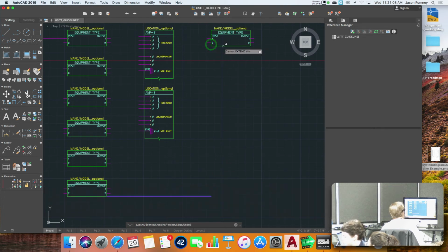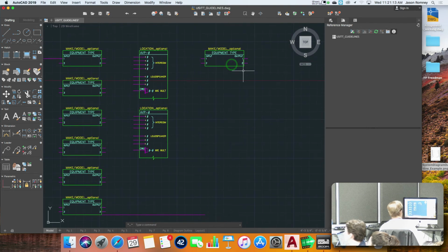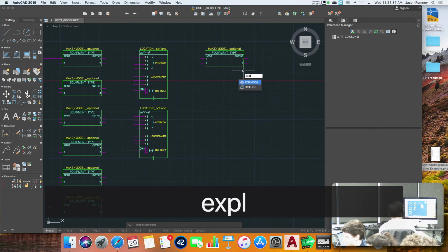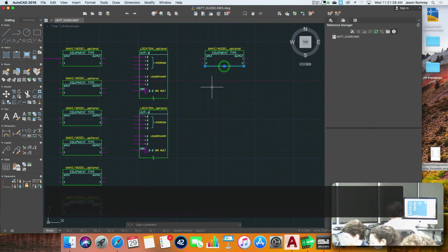Oh, hang on. I have to explode it. Okay. I'm going to teach you one more command. You can use this if you want, but it's a dangerous one. It's called explode. Okay? So what explode does is take a polygon and turn it into individual lines. Okay? So just type explode, and then click on that rectangle, enter. Now that rectangle becomes individual lines. See that?